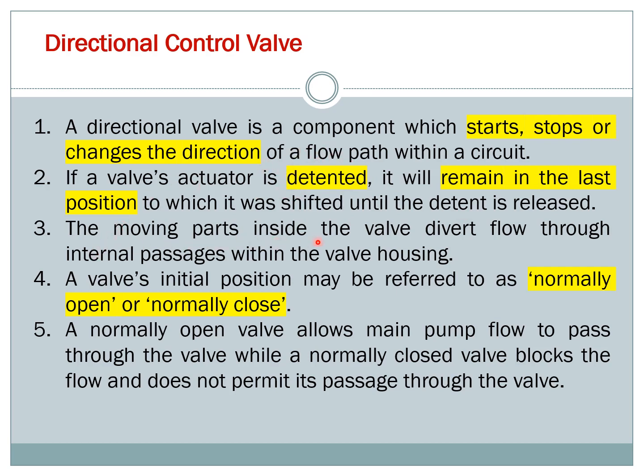The moving part inside the valve diverts flow to the internal passages within the valve housing. Meaning inside your valve you will have a few paths that your hydraulic fluid can follow. That is how the directional control valve controls the hydraulic fluid.